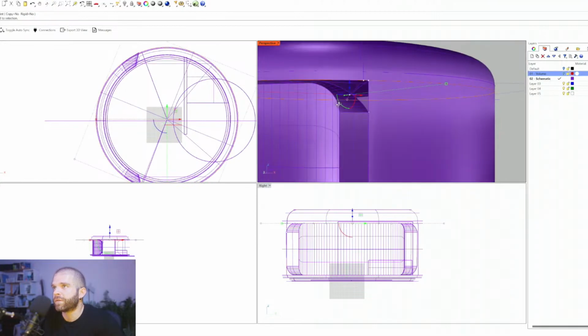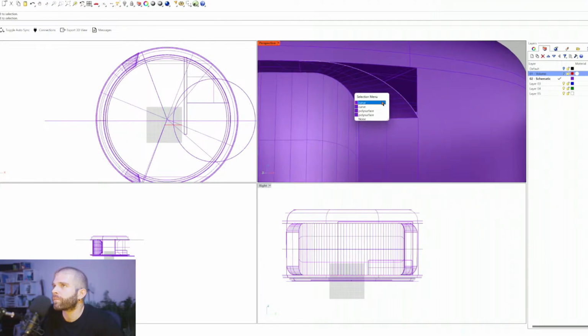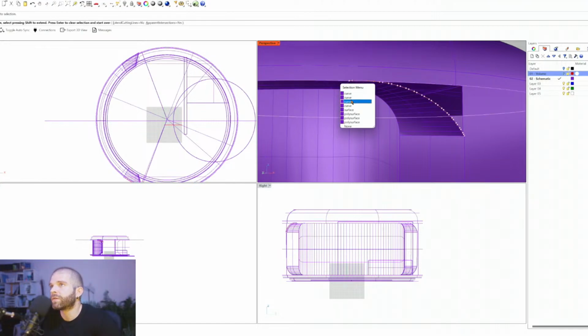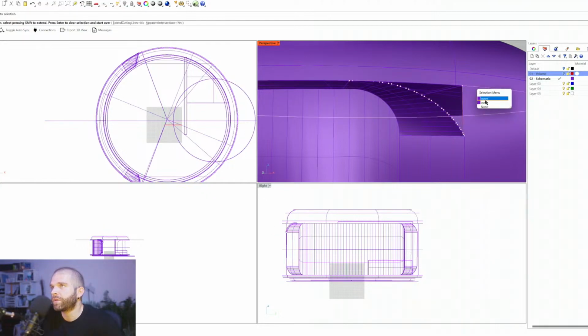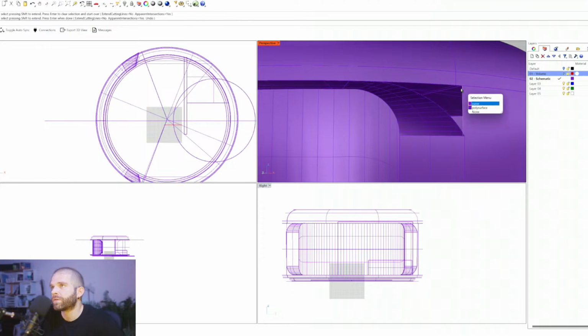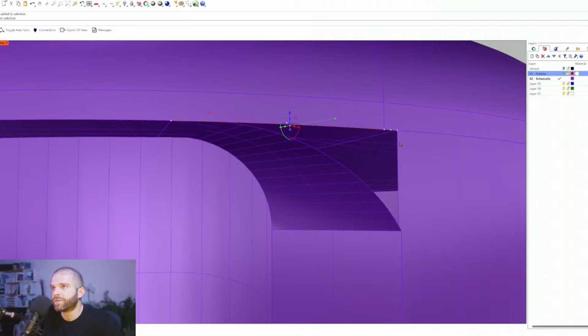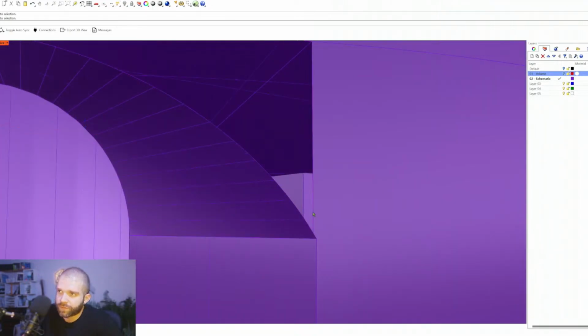And then this one I'm gonna have to trim because it's a whole cylinder. So we'll select this here. There we go, that one curve. Do trim and trim right there. Cool. Same thing over here, trim. Okay, so now if you see highlighted here in orange, we've just got this little open slice in the form of boundaries. Except for this point, they don't quite line up.